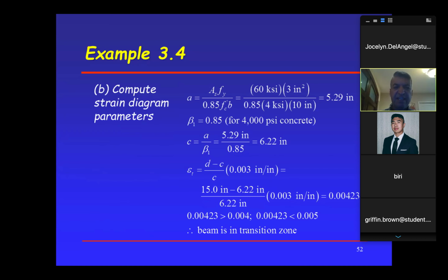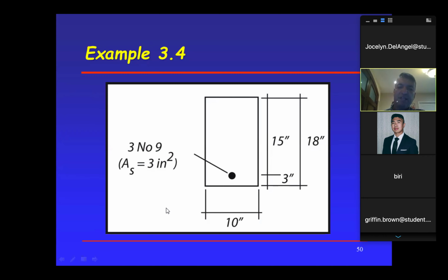All these, as you can see, the examples, the beams are given. The dimensions are given. The steel is given. It doesn't talk anything about loads. Those are analysis problems. Okay? Next chapter, we're not going to be given these beams, the dimensions, not the steel. All they're going to give us is the loads. Remember, this is dimensions given, steel given, how much moment can it carry. In the design, they're going to give us the loads, dead load, live load. From those loads, we're going to calculate the moment, and then we're going to proportion a beam like this to carry that moment.